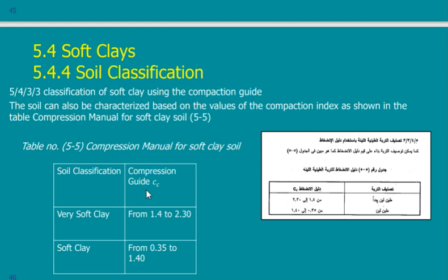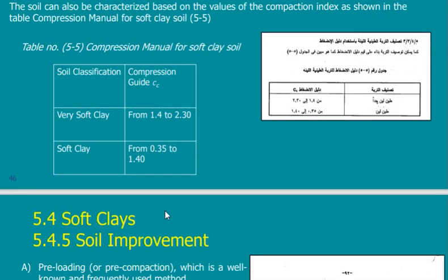in the lab. But remember that when I have a sample at the lab, it means that I could get a sample. So I doubt that I can get these values from the samples that I will get. I will always get soft clay, but very soft clay, it is very difficult for very soft clay to reach the lab. Therefore, it is better to have the test conducted on site, as we said.